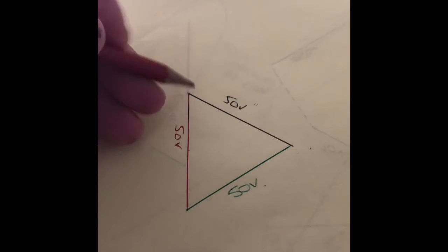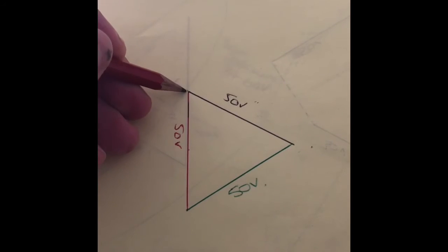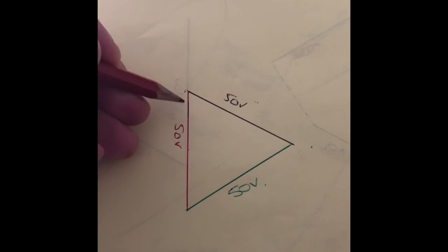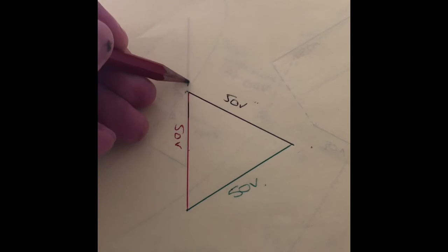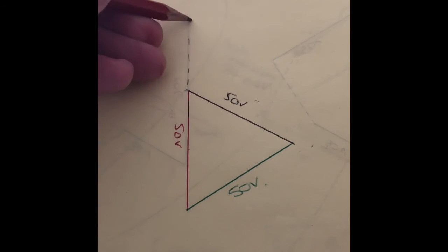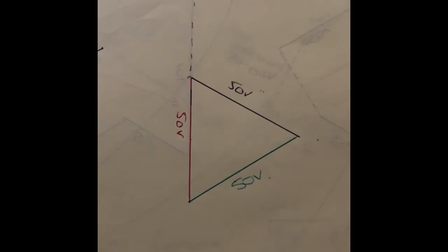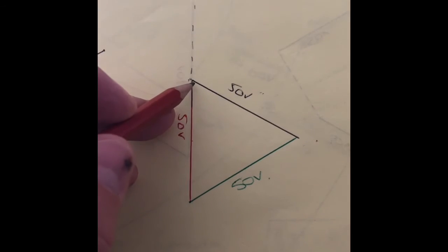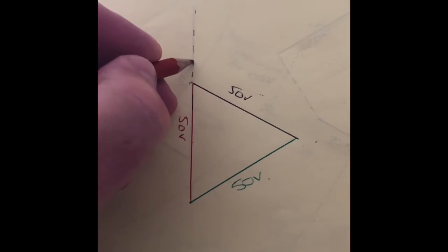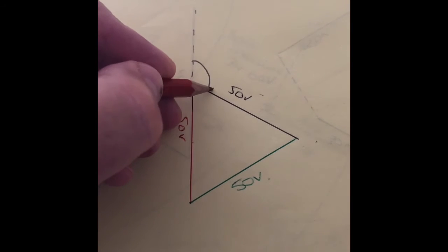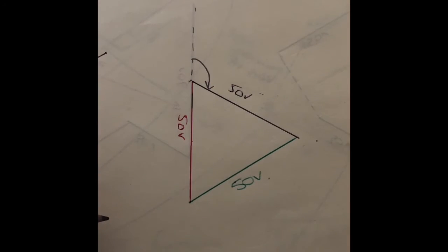What we would firstly do is draw in our phase. So I've drawn this, our 5 centimeter phase. What I would then do is extend the phase, and we know that the phases are 120 degrees offset from each other. So I would then redraw at 120 degrees from this point to here, my phase 2.